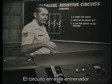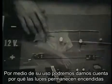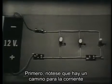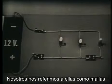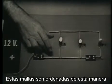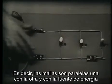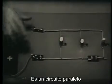The circuit on this trainer is a parallel circuit similar to the parallel string of Christmas tree lights. By using it, we should be able to figure out why the bulbs remain lit. First, notice that there's a separate path for current through each of the bulbs. Now, we refer to these paths as branches. On schematic drawings and sometimes in actual circuits, these branches are laid out as they are here. That is, the branches are parallel to one another and to the power supply. This gives us the name for this type of circuit. It's a parallel circuit.